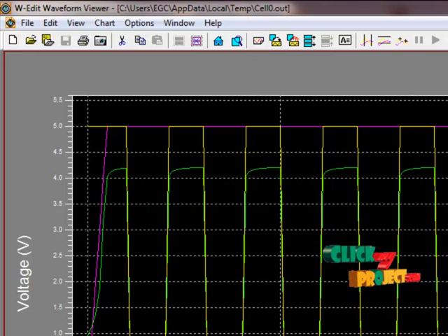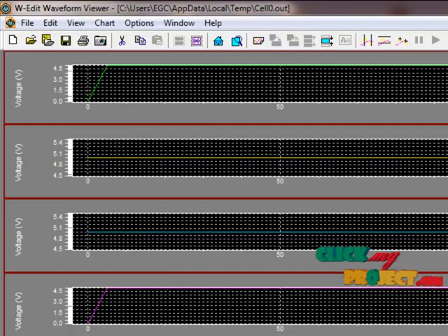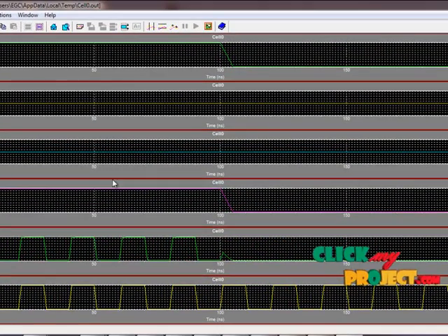We got the outputs for the read WL, the feedback controller, the write bit lines and the read bit lines. This same process we captured from here. We split each and every line's parameter values. So this is the read WL, and this is the feedback line where we are giving 5 volts. Then WWL, the write WL, and for the same time, which port we choose bitwise. So this is a write bit line and this is the read bit line. We choose this port to perform the read process.